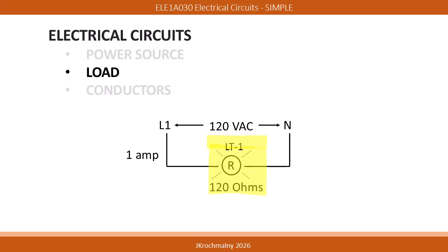The load of the ladder diagram is shown by the symbol representing a red light bulb. Notice the circle representing any load, the diagonal lines coming out from the circle representing a lamp, and the letter R for the color. In this graphic, we see that if measured, this load will register 120 ohms of resistance to the electrical current.